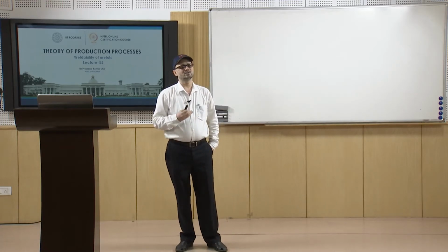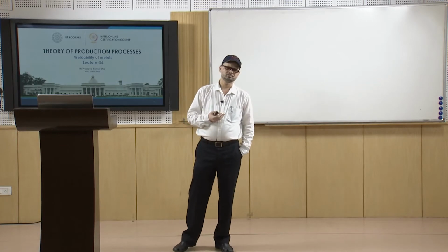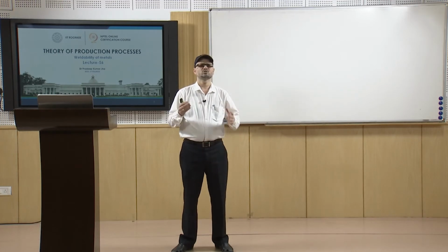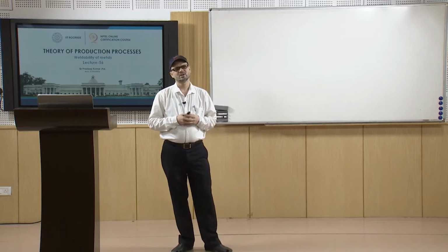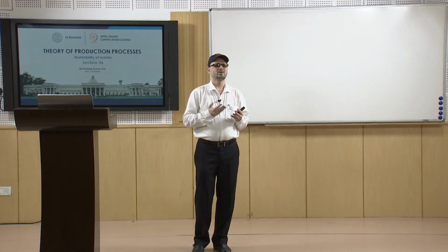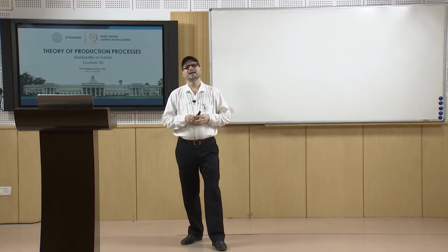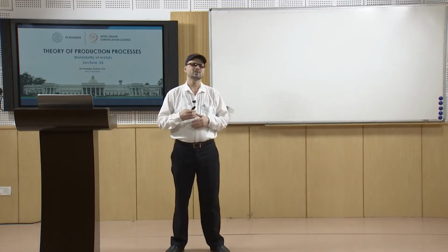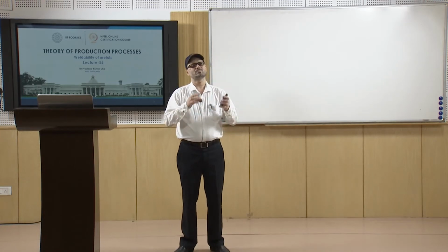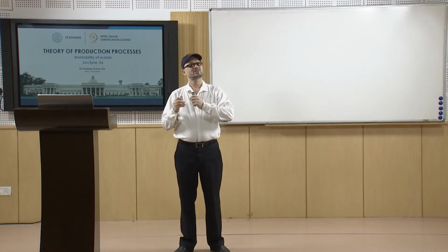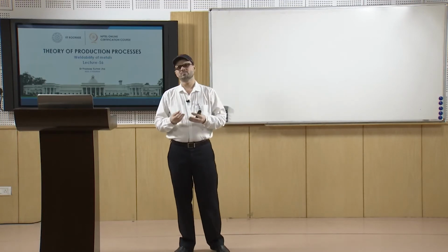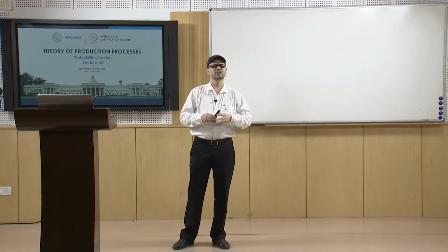Now, when you do the welding, you always feel that the quality of the joint should be better, there should be proper properties, and the properties should not be decreased because of any other factors. So, for that you have to control a lot of things. You have to have proper selection of material, proper selection of electrode, proper selection of operating parameters, proper joint design, fitting and all that.